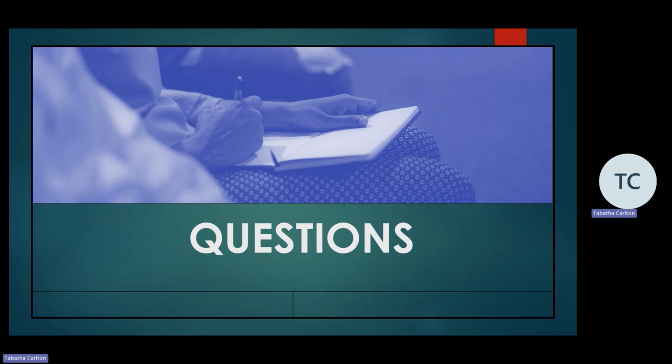Last time I used it was one of the first versions that they were releasing, so maybe I need to go back and give it another shot. But I will say they had problems with the way the reference files were attached. It wasn't saving level displays in sheet files. I'd get my levels set right in the sheet with macros, pop out, come back in, and everything's back. I'd have to plot it right there. But I think they fixed that.